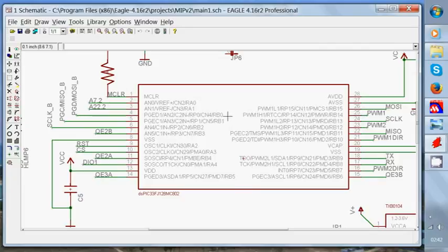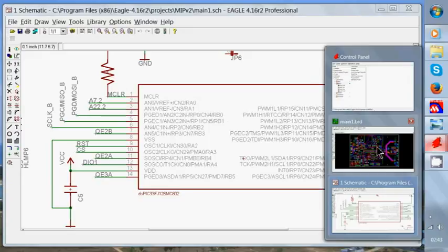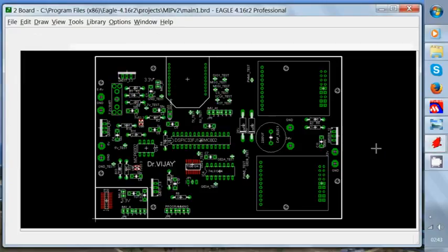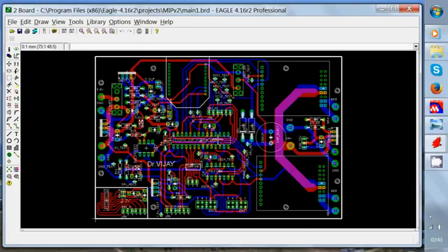Hence there are plenty of registers which need to be initialized in the main program so that the correct peripheral has been connected to this pin for proper functionality. And this can further be used as an advantage in circuit design itself, because the same peripheral could be connected to different pins of the microcontroller. It becomes advantageous to route a particular peripheral in a particular direction of the board, rather than forcing all of them to go on one side.